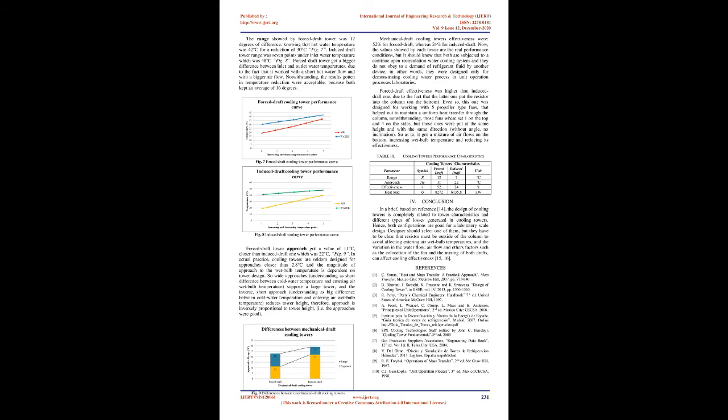Cooling towers characteristics. In the simultaneous mass and heat transfer analysis, the transfer direction and the scope of itself are governed by the balance transfer condition. The conditions of a gas-vapor mixture are shown on a convenient concentration temperature diagram, designed at constant pressure. On this diagram the gas exhaust concentration versus temperature is designed from details commonly obtained by experimental examination for the air thermodynamic conditions such as dry bulb temperature, wet bulb, saturation temperature, absolute humidity, percent relative humidity, and total mass flow of water per hour through the tower, which are the starting point to define laboratory scale cooling tower parameters.